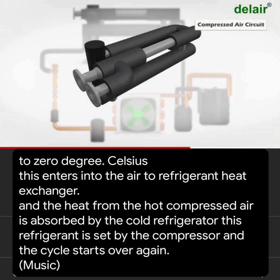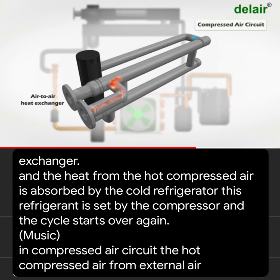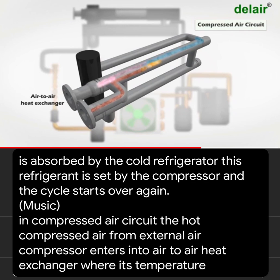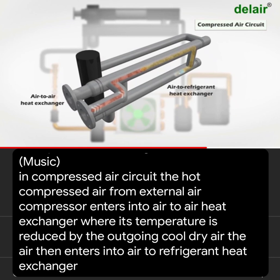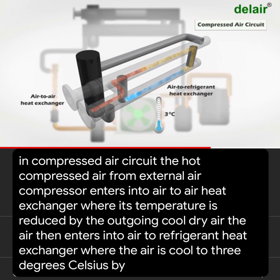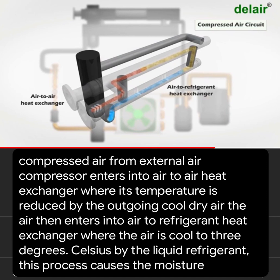In the compressed air circuit, the hot compressed air from the external air compressor enters into the air-to-air heat exchanger, where its temperature is reduced by the outgoing cool dry air. The air then enters into the air-to-refrigerant heat exchanger, where the air is cooled to 3 degrees Celsius by the liquid refrigerant. This process causes the moisture to condense into liquid water.